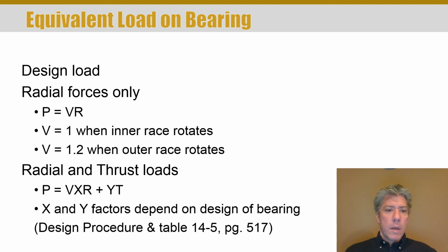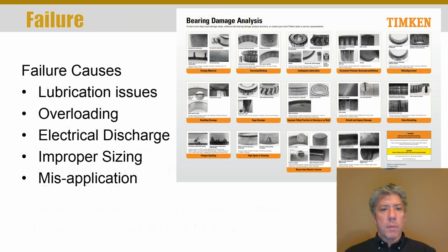And if there's some other more complicated sizing equation that a manufacturer has, you should learn to use it. We're just trying to introduce you to the concepts needed to understand them. Also, typically in bearing application, if it's a critical application, you really need to get with an application engineer from the company where you intend to buy the bearing, and make sure that the bearing that you select is appropriate for the given application. Now, the Y factor depends a lot on the ratio of the thrust to radial load. There's a whole design procedure that you need to tab, so this is another page worth tabbing, and the details I'll go into in an example problem.